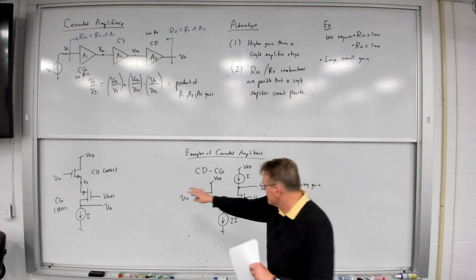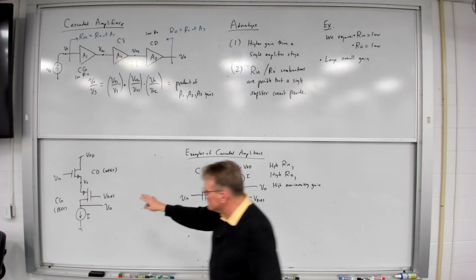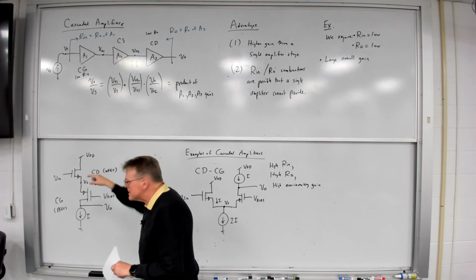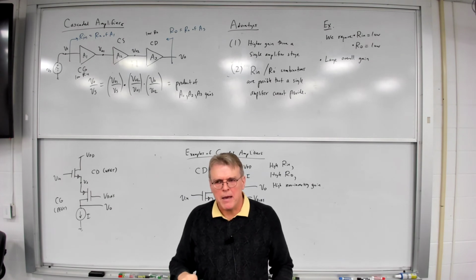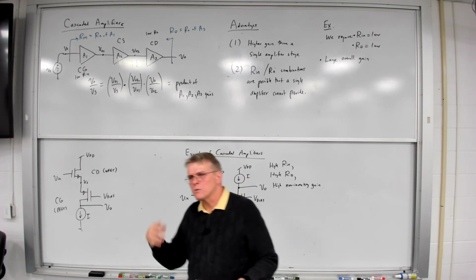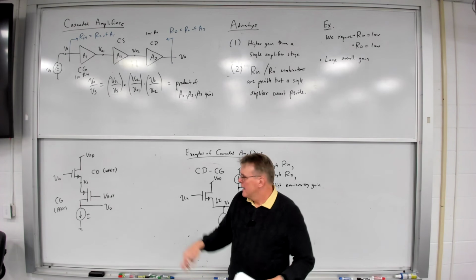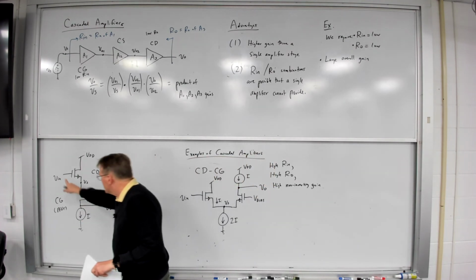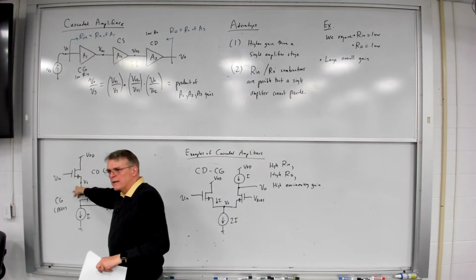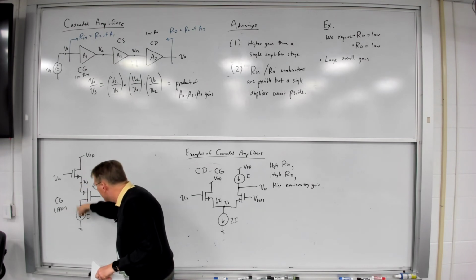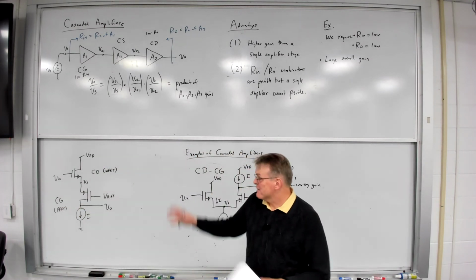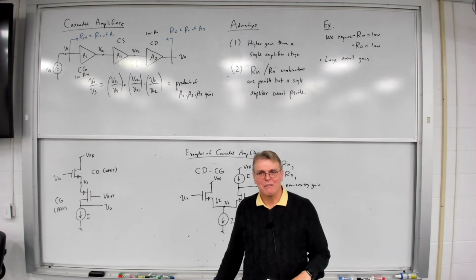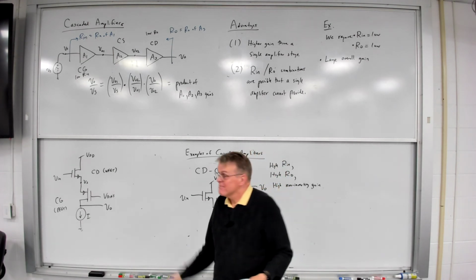And when you sit here and look at these multi-amplifier topologies, quite often you have to look at each transistor and think, what's that acting like? Is it acting like a common emitter, or a common base, or a common collector, or a common source, or a common gate, or a common drain? And you have to trace the signal path. You say, oh, from here to here, that transistor is acting like a common drain. That's a source follower. Then from here to here, it's going into the source, coming out the drain. That's acting like a common gate. Except that it's a much more compact and elegant design. The way we're saving components. Pretty cool.